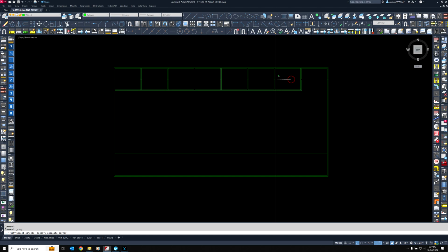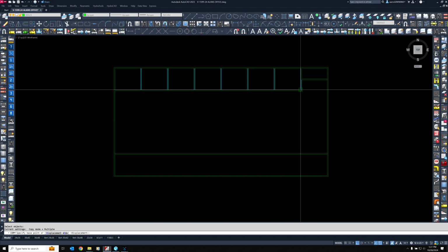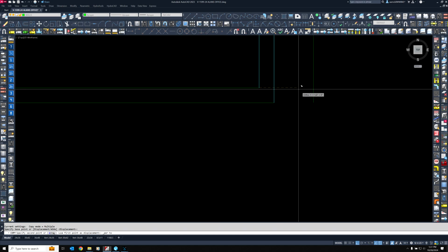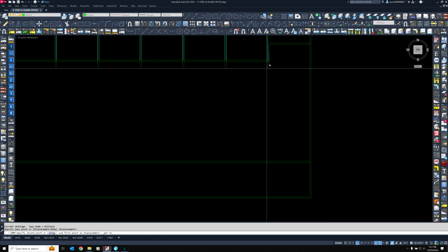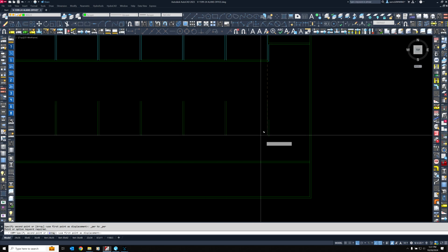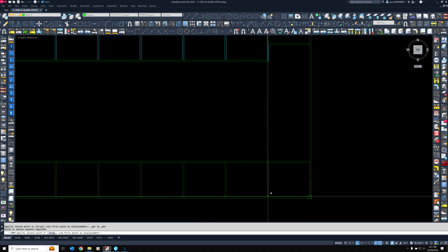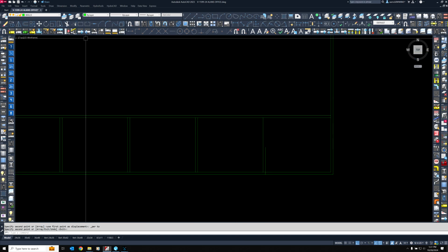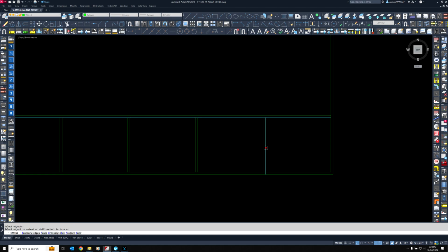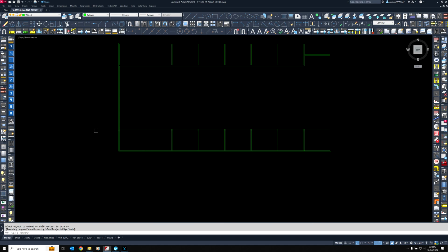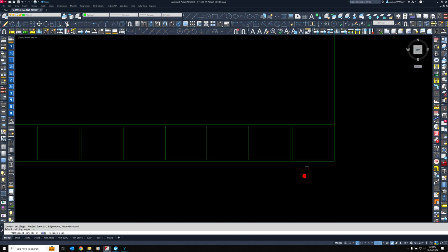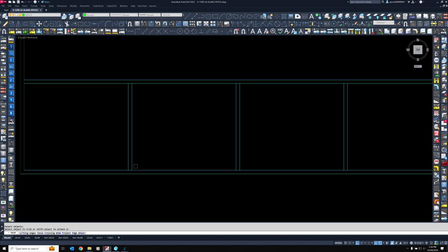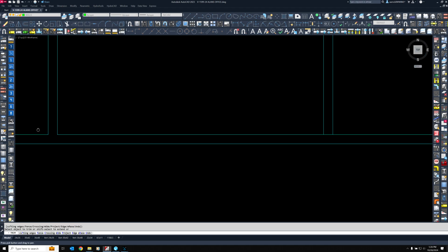Okay, let's go ahead and finish the bottom end, which we also could have done a different way, but I'm going to just copy those from this base point, not this one. From that base point, hit the perpendicular button, and we're going to take these all the way down here. Too many times, perpendicular, and you'll see that lights up. Hit the extend button, left click, enter, left click. Now we have our offices all the way across the bottom of this building. I'm going to grab all of it. It should cooperate. Snip out our overlaps.